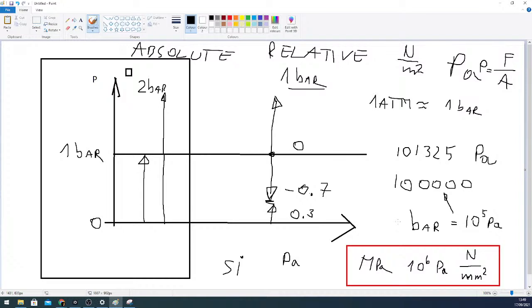So the piston size may be, for example, 10 millimeters, 16 millimeters, 50, 40, 63 millimeters. We are usually interested in millimeters as a unit, and megapascal already has the units in millimeters. Therefore, this is recommended to use in calculations.